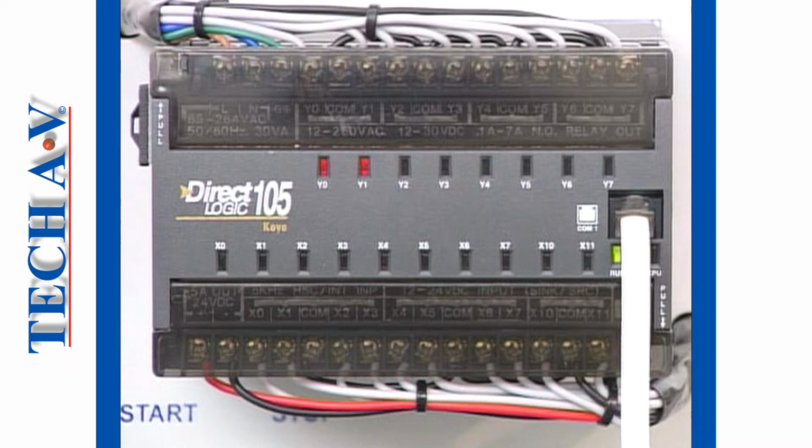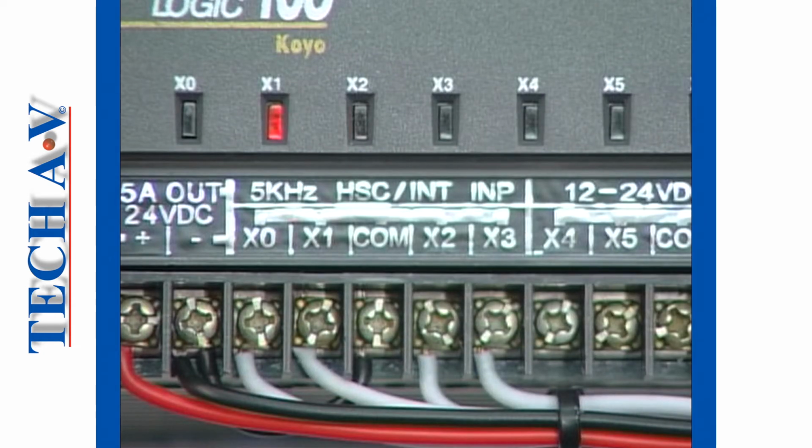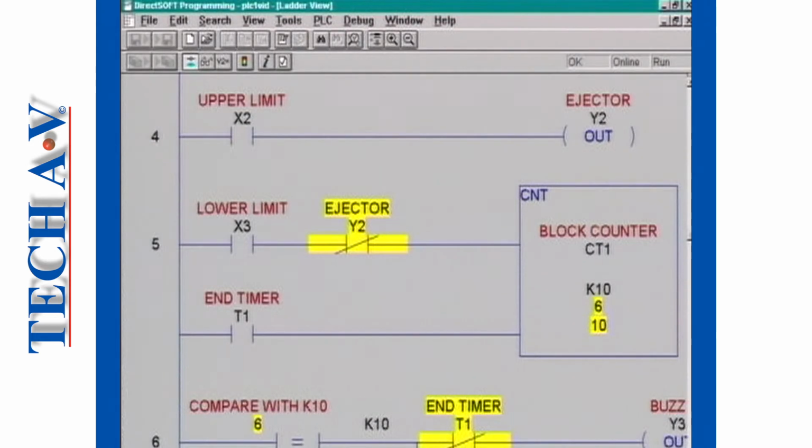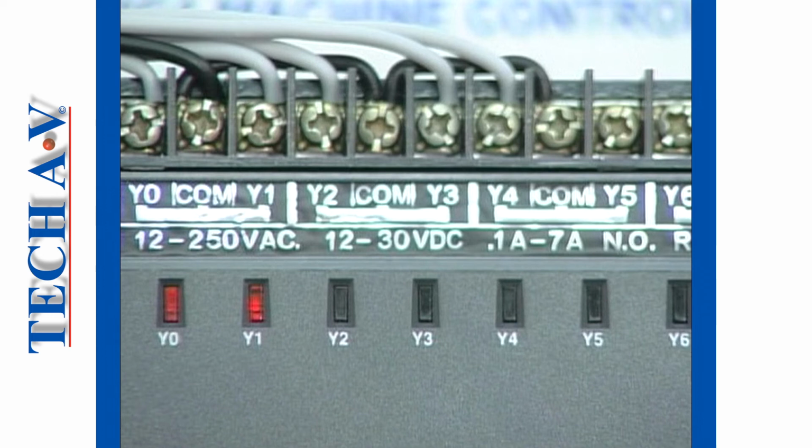Now let's begin Module 4 and find out how the PLC processes information. As we know, the PLC has no moving parts, but several times every second it examines each input location, reading and recording the state of the inputs. Then, following the user program, which we represent as a ladder logic diagram, it decides what the state of each output should be, and then it activates the outputs.